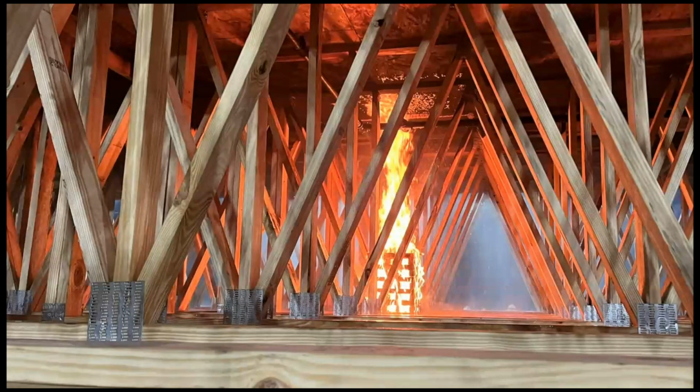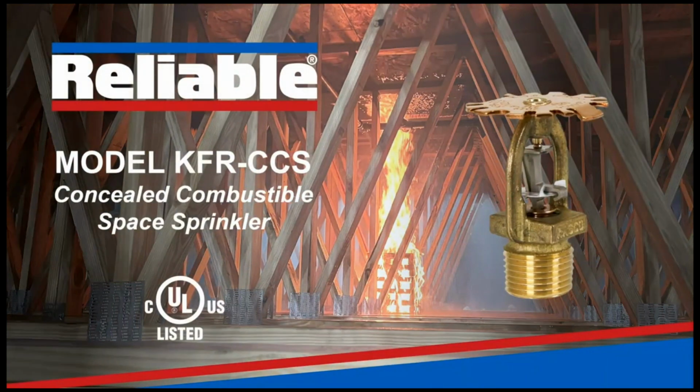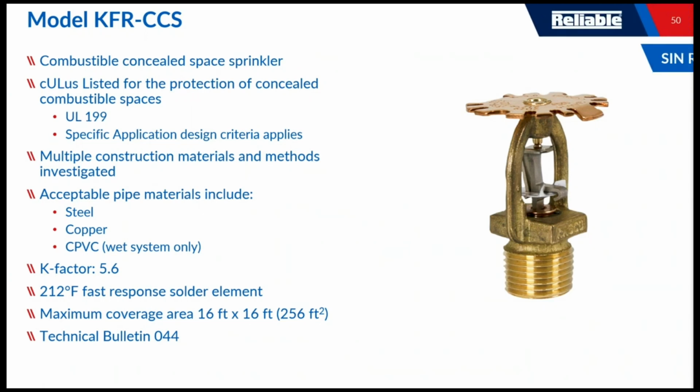So, shifting gears, moving on to another sprinkler. We're going to talk about our concealed combustible spray sprinkler. It's the model KFR CCS. These types of sprinklers are meant to be used in combustible construction, primarily in between floors, in between spaces. This is listed at UL under 199. They investigate multiple types of construction materials and methods of building these floor assemblies to try and give you a good cross section to pick the different types of construction, and then also pairing it with the pipe material that you're probably going to be using.